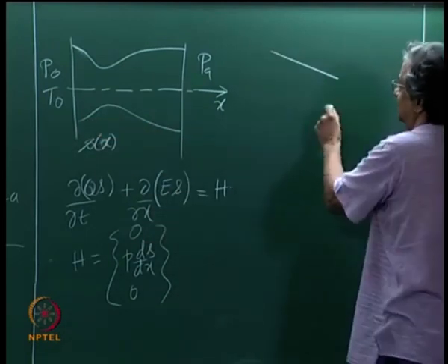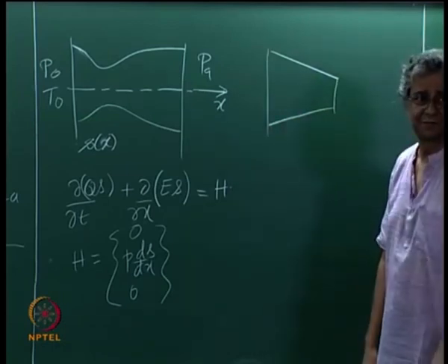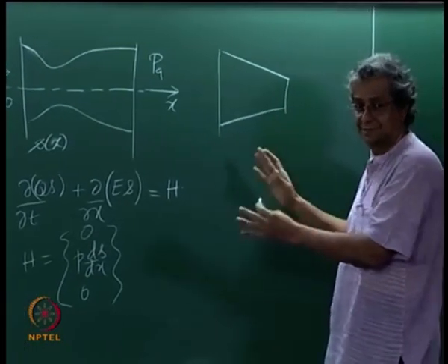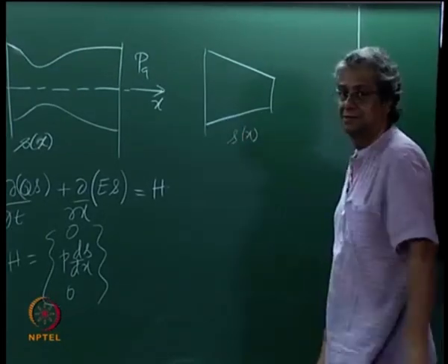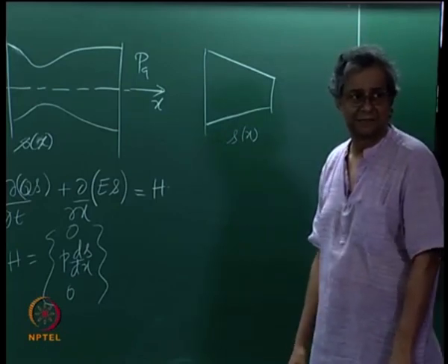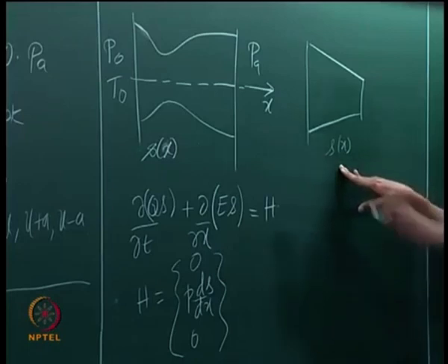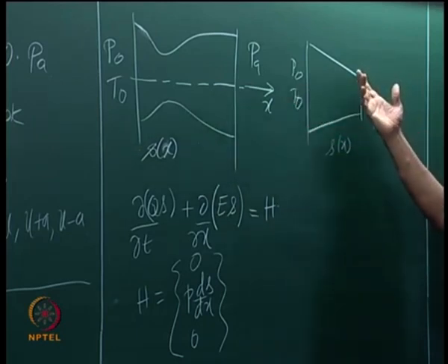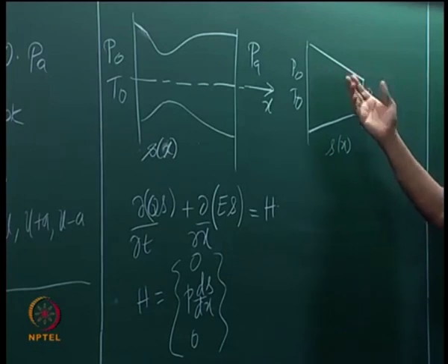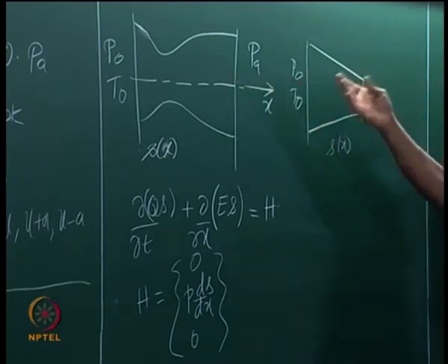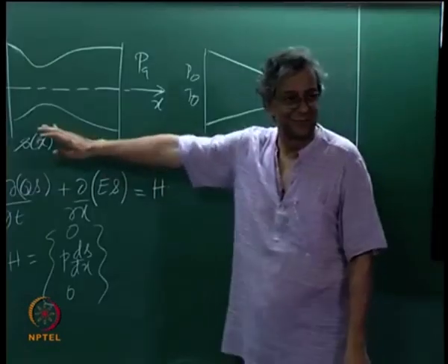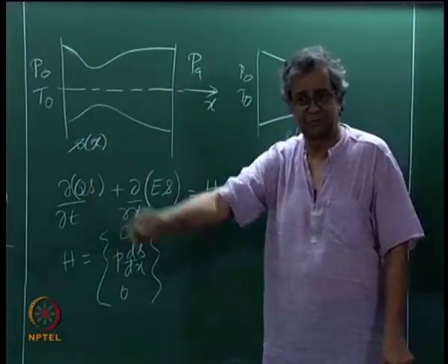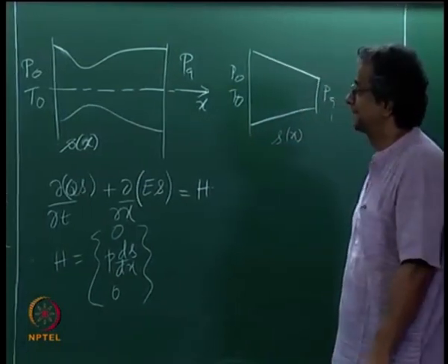I would just do a small converging duct, instead of a constant area duct. So the S of x is known, S of x is simple, a linearly decreasing function. Prescribe the P0 and T0 here, prescribe P ambient here, in fact you can take the same values that are there, see what happens, okay, is that fine. I would most probably then do a diverging section and then maybe a CD nozzle at that time. It is always good to go through a hierarchy of problems instead of jumping into the big problem directly. Are there any questions?